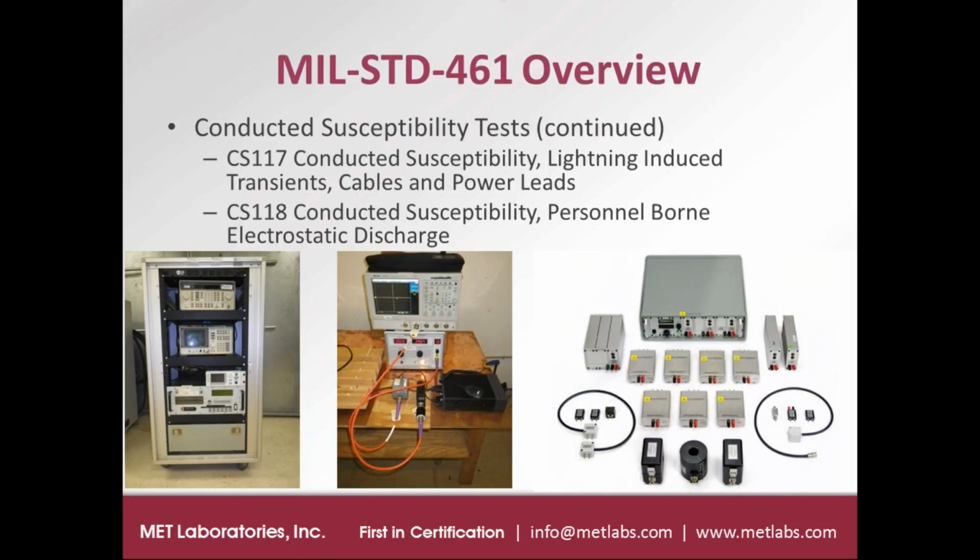And there are two more conducted susceptibility tests, and these are new to version G of 461. CS117 is a lightning-induced transient test, mostly taken from the method that has existed in RTCA DO-160 for commercial aircraft for quite some time. And then CS118 is electrostatic discharge, a test that has been done historically since EMC testing has been performed, and they use the method from IEC 61000-4-2, which is the same test method that's used for devices sold with a CE mark in Europe, as well as many other types of products.